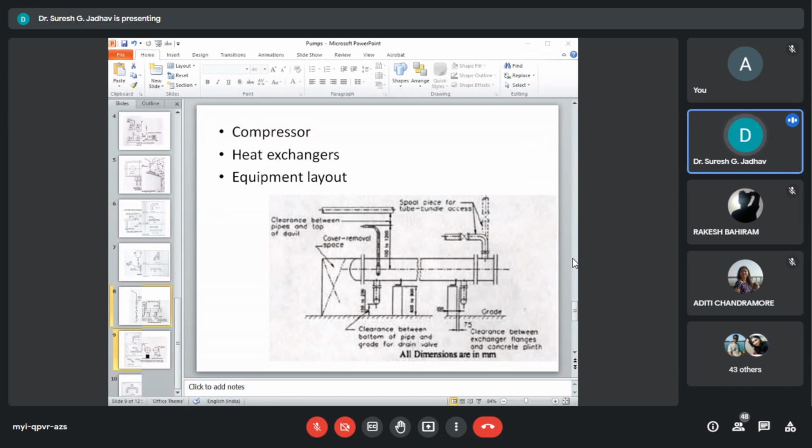The hand-operated traveling crane located at compressor center line is to be provided overhead. The laydown space also has to be planned for. Knockout drums and interstage exchangers are also arranged so as to have short and simple piping.